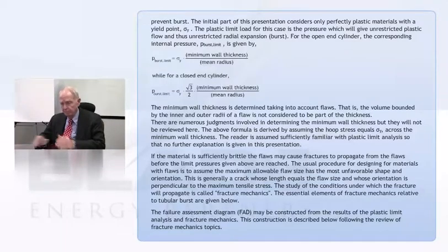And in particular, when you get to the last step that we're going to take, what we do is combine the results of all the stuff about the fractures and the cracks and such, and we combine that with the overall plastic behavior. And what it turns out, of course, is that the flaws don't help you; they hurt you. So you would have to scale down a design based on flaw size, and that's where the failure assessment diagram comes in. So we've got a ways to go to get to it, but that's where we're headed.